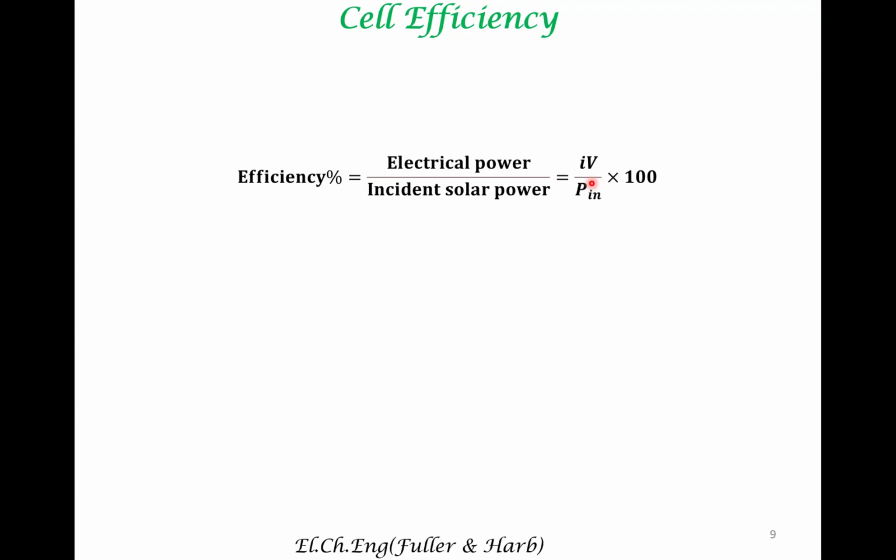Why do you say that? Because electrolyzers are fairly efficient, about 60 to 70% efficient. And if you have an inexpensive solar cell, let's say an amorphous solar cell, that is about 10% efficient. So 10% times 60 to 70%, the photoelectrochemical system should have 7% efficiency. So these are target efficiencies.